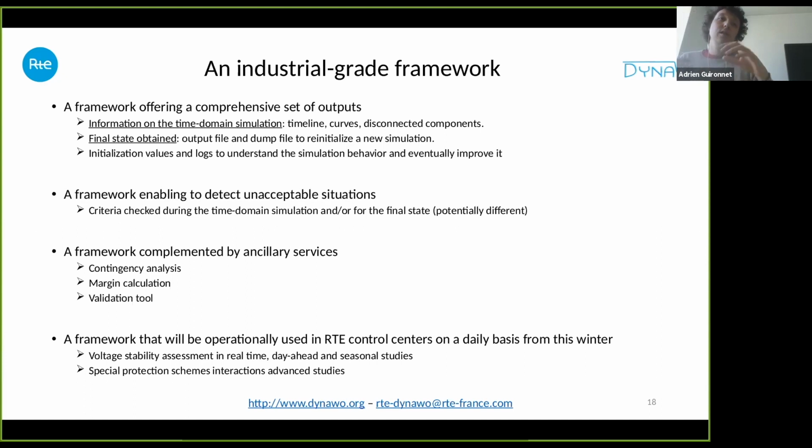In addition to the unitary simulation aspects, you also have ancillary services to launch multiple simulations that are very common usage in the power system community, such as the contingency analysis, where you will just disconnect one by one all the components and see what the effects are, also margin calculation or validation tool, being able to launch the simulation several times and compare the results if you change this parameter or this model.